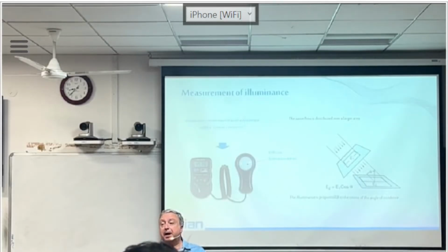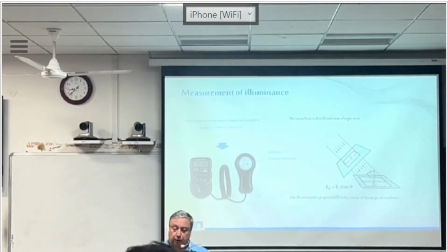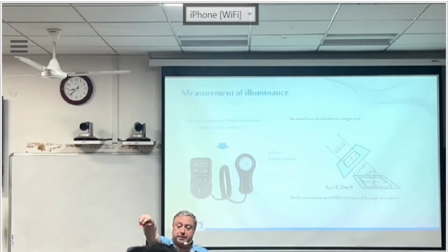The very cheap instruments, less than 500 euros, are not calibrated, because a single calibration point is globally 500 euros. And normally in a metrology lab, you have to calibrate all your instruments at least once per year and have the calibration certificate. When you buy something for 4,000 rupees, it's not calibrated, so you cannot measure the illuminance here, but you can say here I have 2 times more illuminance than here. In relative terms, it works okay.